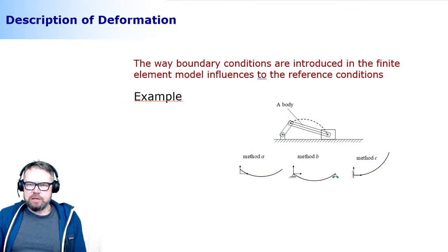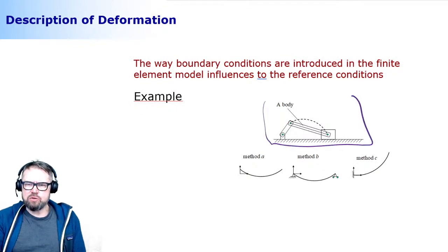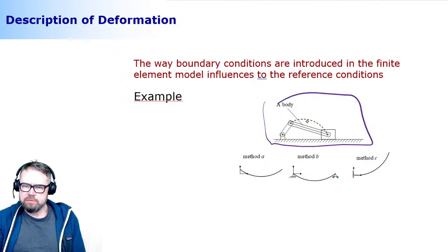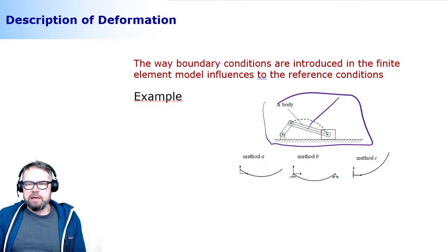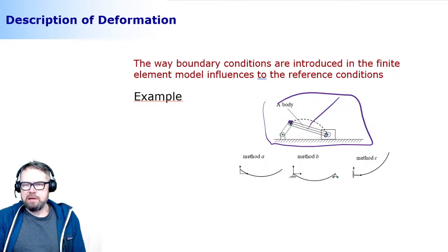Now, I want to take a look at the structure that is shown here, and this is a structure that we know very well. So this is a crankshaft mechanism, and I wanted to model the connection rod, this one here, using a floating frame of reference formulation. And you see how it is connected to neighboring bodies, which is a crank here by a revolute joint and a piston by a revolute joint. So this kind of resembles a simply supported beam boundary condition.